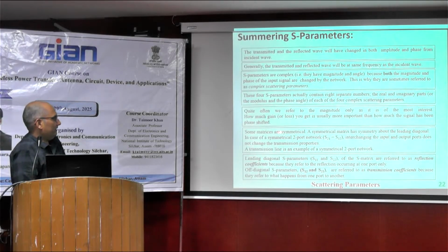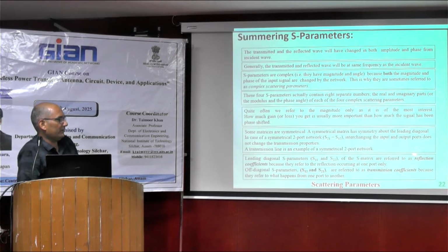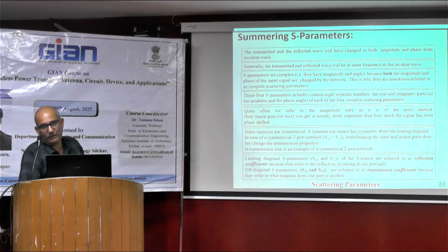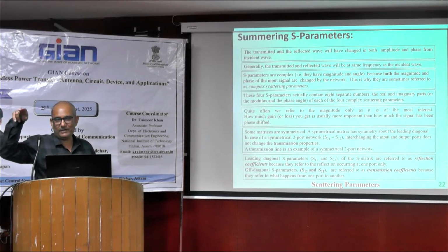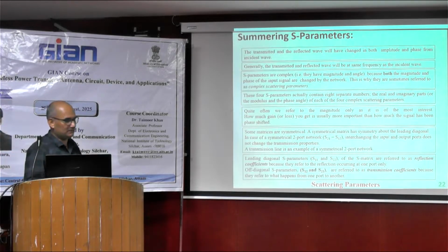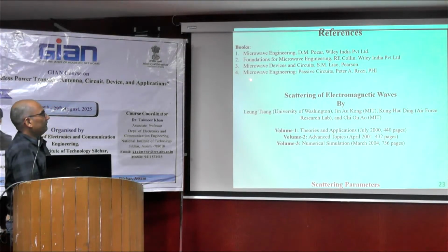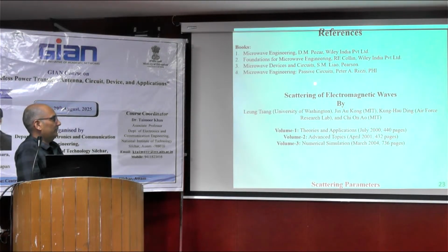On the leading diagonal, S11 and S22 are known as the reflection coefficients because they refer to the reflection occurring at one port only. The off-diagonal parameters, S12 and S21, refer to the transmission coefficients. One is forward transmission, the second is reverse transmission. That's why the terms forward for one parameter and reverse for another come into the picture. These are a few references that we can take.